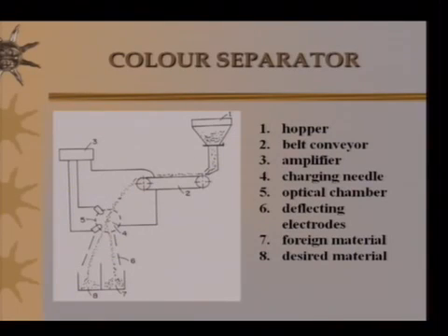Now there the problem is that many of the rice kernels change in color. Instead of white, they are amber in color. So that is a problem. They have to be removed and only white kernels have to go. In that case, the color separator can be used. The other kind of thing could be if you want to differentiate between kacha fruits and pakka fruits, for example, green color apples from the red color apples, again the color separators can be used. So the color separator can be used in any industry, and I would just like to tell you about this.